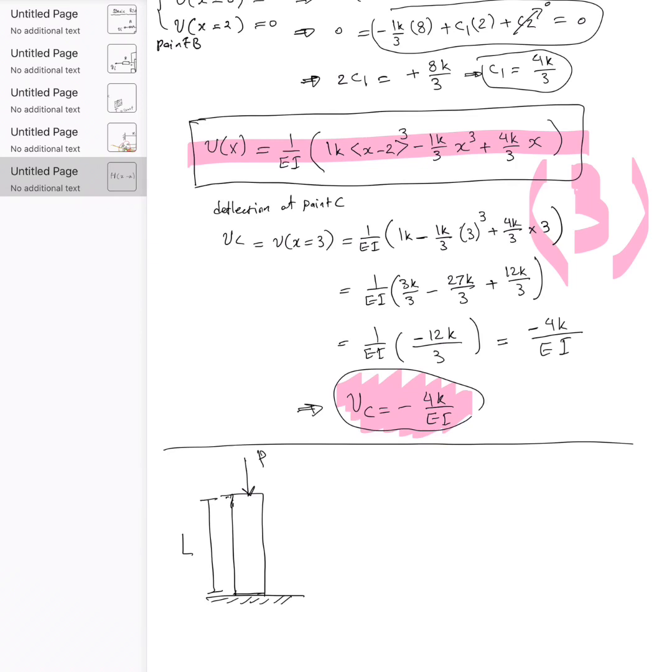But after some particular point, this is going to start to buckle. That means this is going to go like a bow-shaped profile. And in this case, the equation, when we do F over A is equal to E delta L over L, is no longer valid after it buckles.